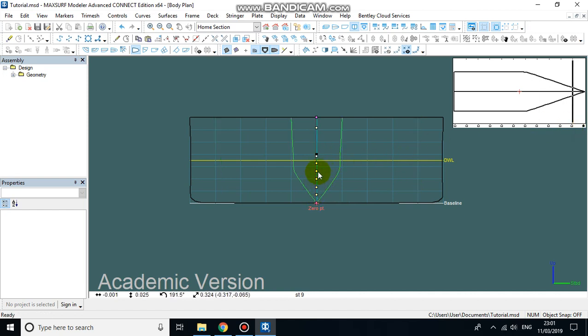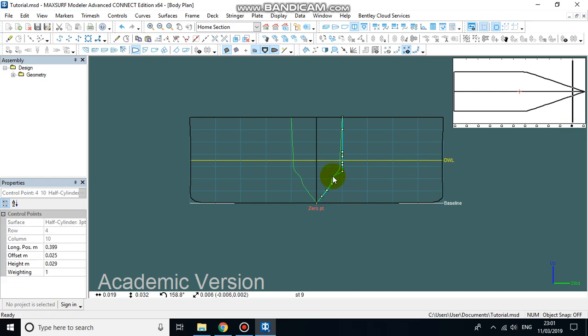We know that all of these should land on the centre line, and that means that the hull is closed at the front. Then it comes down to a simple process of dragging these to the shape that you want, and seeing what that does to the overall hull shape itself.